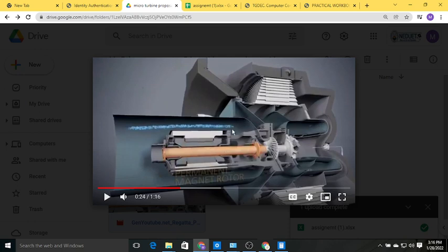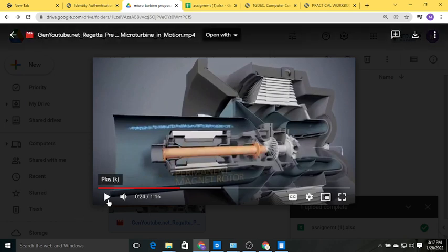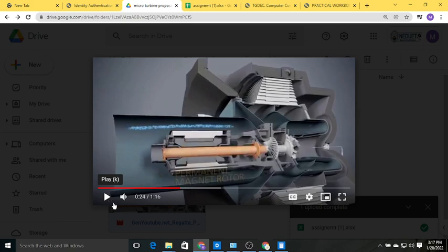The system is like this: the compressor sucks air from this point, it goes into the heat exchanger, taking heat from exhaust gases, then goes into the combustion chamber. In the combustion chamber, high temperature and pressure gases go into the turbine, and after combustion the gases are released through the heat exchanger. Those exhaust gases also heat the inlet air after the compressor. So it's a very efficient system, with efficiency like 50-60%, not 45, sorry.